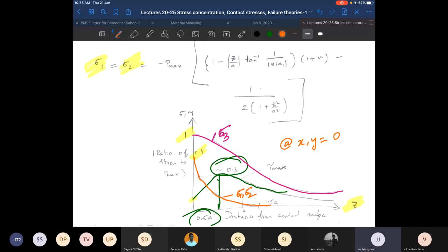So for finding the stress concentration factors, we use the graphs for the features, right? Right. So for contact between, say, hybrid materials, you can either use the graphs or you can use finite element analysis. You can use both of them. For the newer materials or not so common materials, we use the analysis? It has got nothing to do with materials. It is more about geometry and loading.